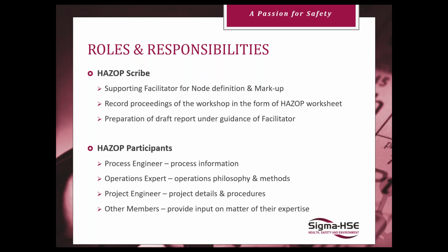If they're maintenance, is there a method they're performing tube bundle maintenance with, where it's not designed for it, but it's been common practice now, you drop, say, a tube bundle head without flushing the system? Do we need to call out that it requires a purge procedure first? What are they doing that may have a risk that the design engineers wouldn't be able to identify? And how can we address those needs?